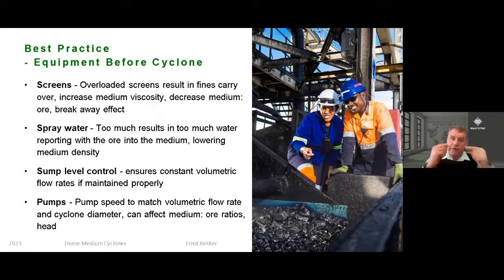Because if you carry over fines, there's also ultrafine material that is going to be smaller than the apertures of your drain and rinse screen. And in the drain section, that fine material is now going to start accumulating. And there goes the medium viscosity. Decrease in the medium to ore ratio, because you are sending more tons now to the mixing box if you overload your screens. And then this breakaway effect to keep in mind.